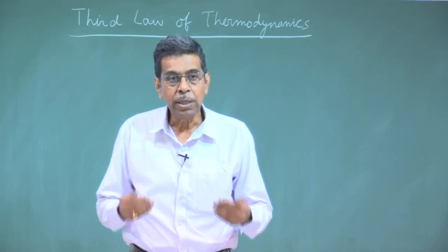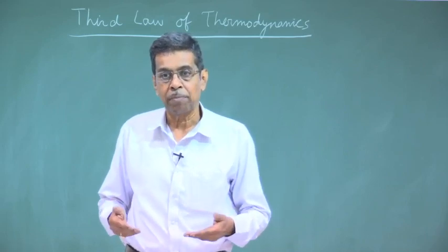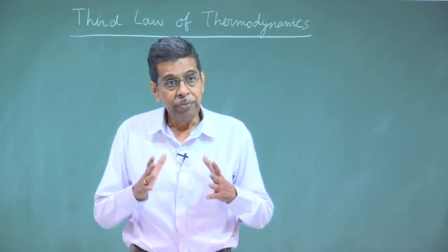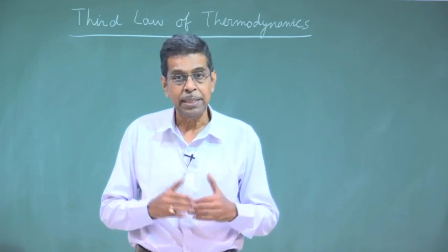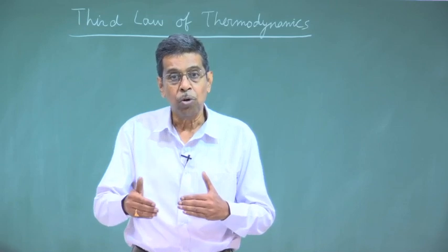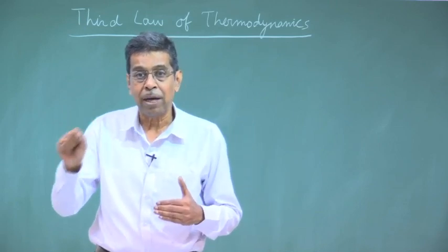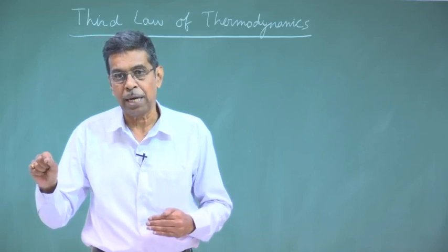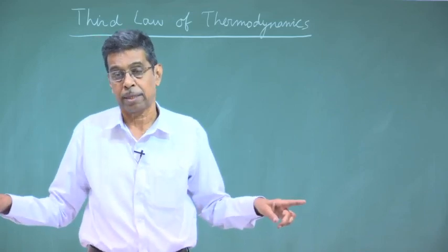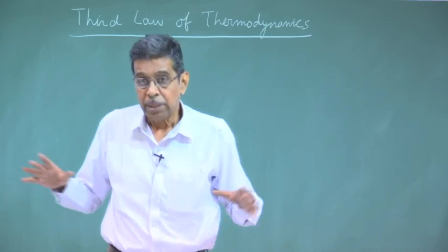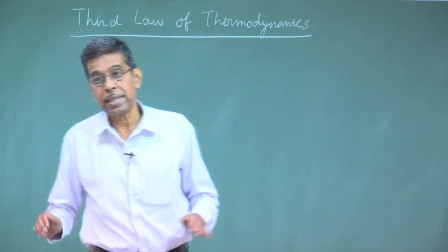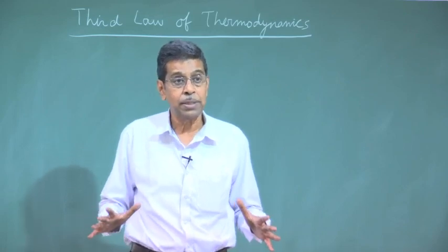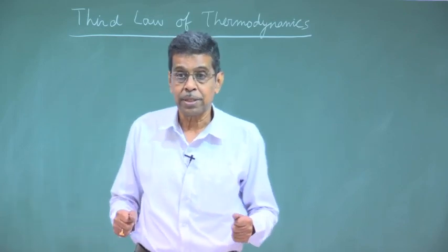In all engineering calculations the changes are required, but sometimes we require the absolute entropy. Even if we don't require absolute entropy, the changes are known, but if you have to ascribe a value of entropy, it is not exactly the absolute entropy from an absolute datum, but you have to fix a common datum. The third law of thermodynamics tells that common datum where the entropy can be taken as 0, or entropy is actually 0 of a substance.